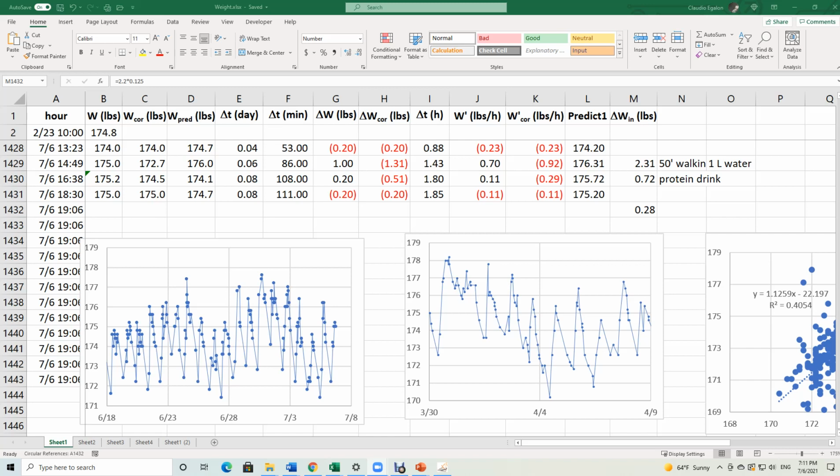Here you go. Two LEDs in series. They should light up unless I did something wrong. Oh yeah, I connected it in the wrong place. This one is switched. Okay, see that? LEDs in series, right? They are both lighting up. I remove this LED as though it has been burned out, and the other LED stops working as well. Put it back, both LEDs turn on.